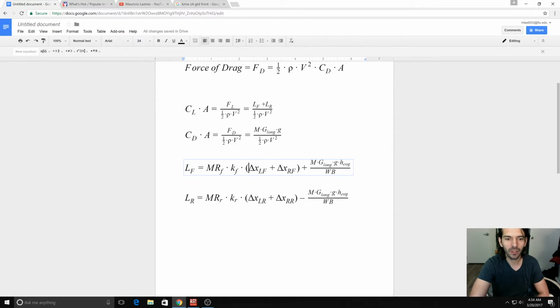We're going to calculate the force on the springs due to weight transfer. So what is that? That's the spring rate times the final position minus the initial position. We always know what the suspension position of the car is; that's easily given to us. But what we need to find out is the zero position. So we'll have to calculate what the zero position of the suspension is, so that we can subtract how much